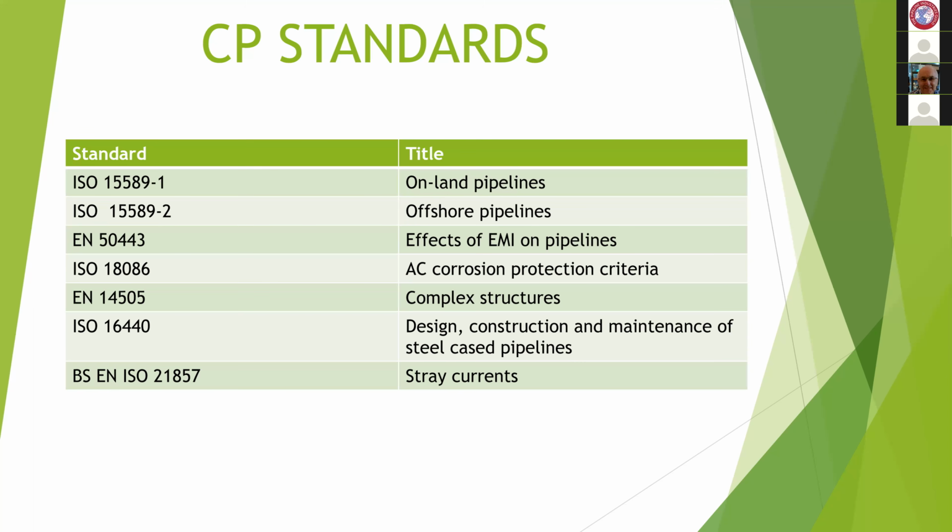And once that water's in contact with the internal pipe, or once the air inside is moist, then there's the risk of corrosion if there's any coating damage. And the risk of coating damage is greater for a pipe inside a casing because of the damage that often occurs when they're pulling it through.